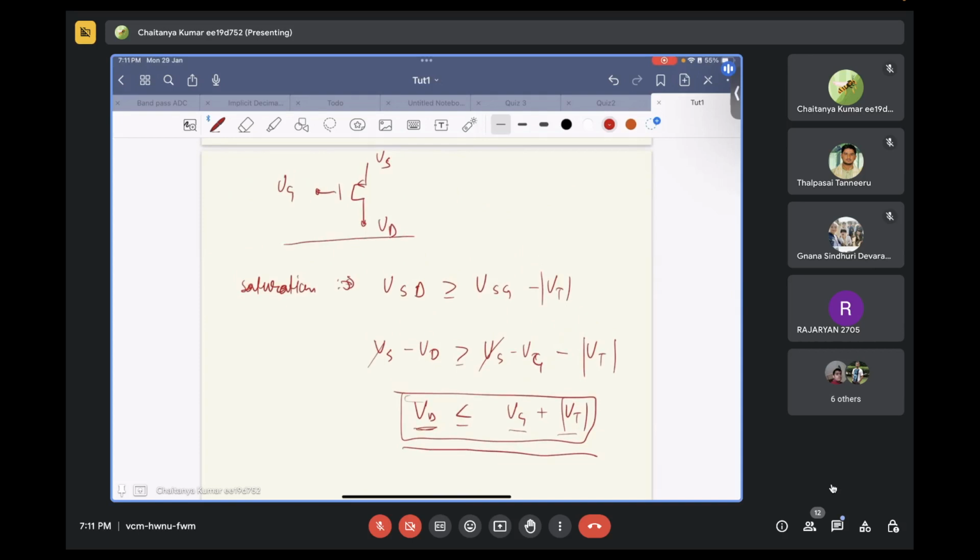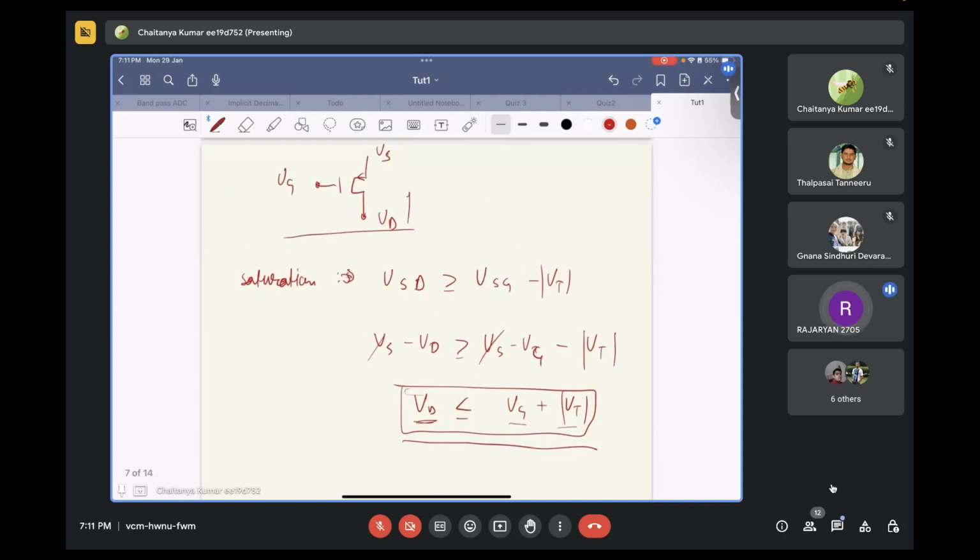So here is a PMOS. In English, how will you say this? The maximum value of VD should be one times VT above VG. One times more absolute value of Vt. Yes. Like for PMOS, Vt is a negative quantity. When you are saying one times above Vt, you mean to say absolute value of Vt, not the actual Vt.